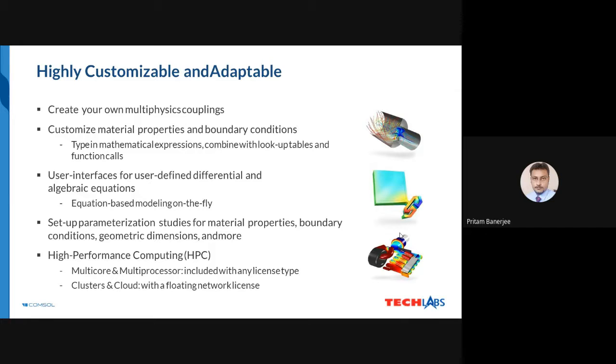You don't even have to bother about it. Suppose you are selecting joule heating physics, then the equation that is actually getting solved, every equation it will automatically take, and it will automatically show you what equations, what physics, the details of that physics, what algorithm it is using, what solver it is using. All those details will also be available from the list.